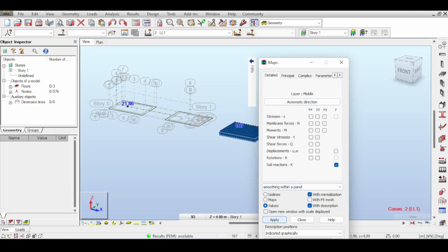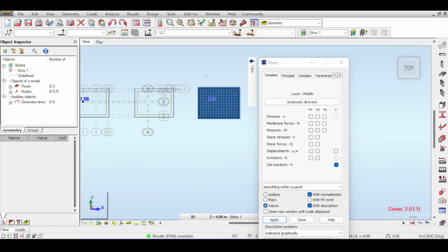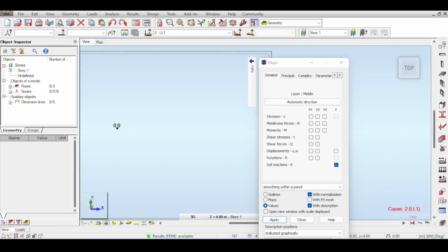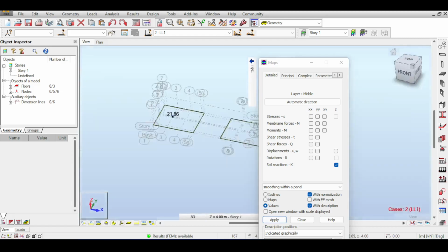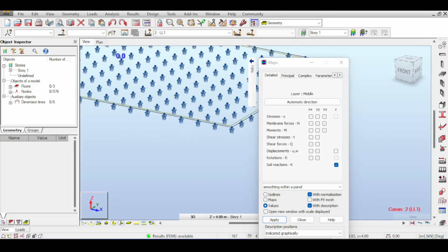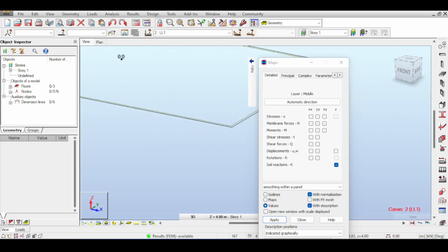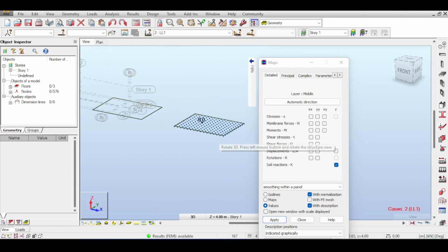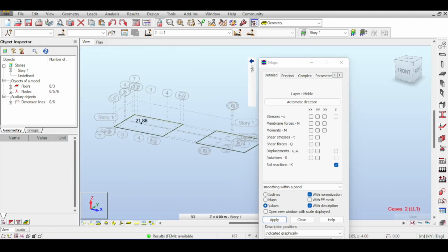So let's talk about this. Sorry, I need to collect my thoughts because I'm a little bit ecstatic now. All right, so to collect our thoughts, I was able to mimic the foundation by basically putting tons of springs below the foundation. And this actually gives me an idea to implement in my software Strado, but I'll keep this in my head myself. So I mimicked the foundation by putting tons of springs, and you can see that this works just fine.